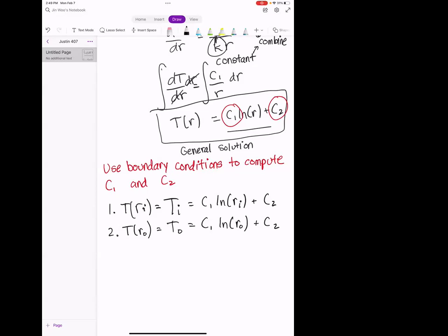For the case on the homework, for problem 2 specifically, one side is being heated by the electric heater, and so that's why you apply that boundary condition there. Whereas the other side is being cooled by convection, so that's why we use a convection boundary condition on the other side. In this case, we have prescribed temperatures, so it's pretty simple. But you have to look at what the problem gives you before you decide what boundary conditions you want to apply.